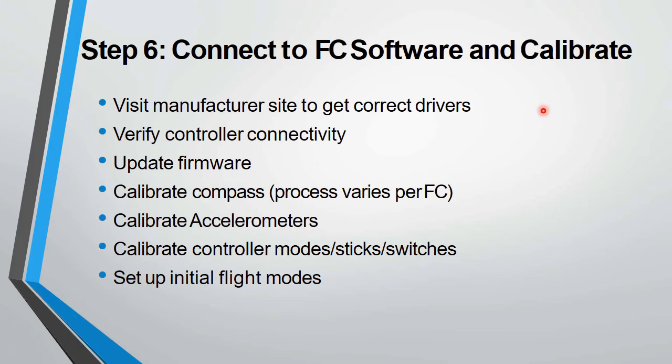Now visit the manufacturer site to get the correct drivers, verify controller connectivity, update firmware, calibrate the compass (the process varies per FC), calibrate accelerometers, and calibrate controller modes, sticks, and switches, and then finally set up initial flight modes.